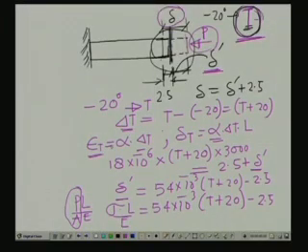But when it is giving a thrust on the wall, the wall gives a reactive force, which is causing an internal stress in the member. And so, we have derived this equation based on the deformation compatibility, which we call the compatibility equation. And so, the change in the temperature is basically an indeterminate system, and we solve the problem in indeterminate form.